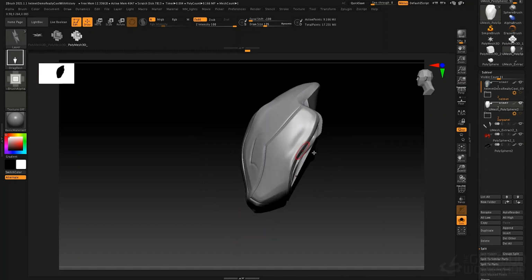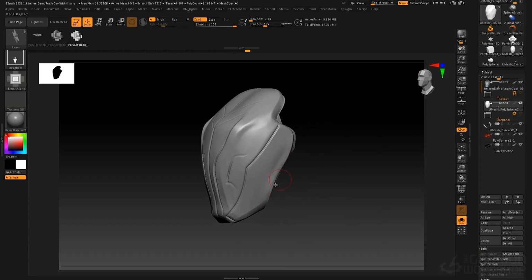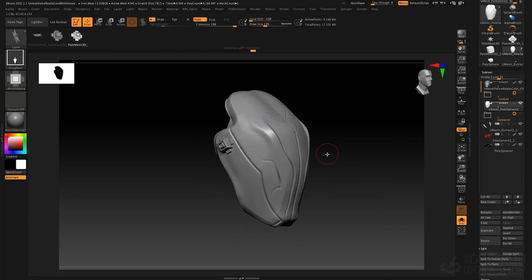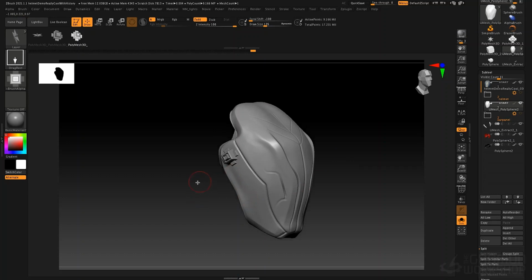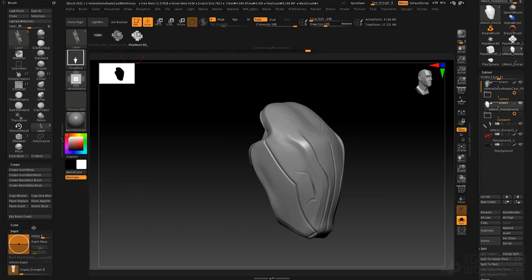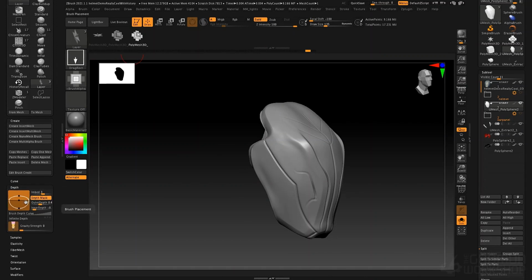So I'd like to put a couple greeble details onto this helmet. So we'll put these sort of sockets right here. Place those at about that point there. Now, if they are too high, maybe I want to clip them. I can undo that, remember, with Control-Z, and we'll go to our brush menu. Let's tear this off on the side of the screen. Come down here to depth, and remember, we can depth mask this.